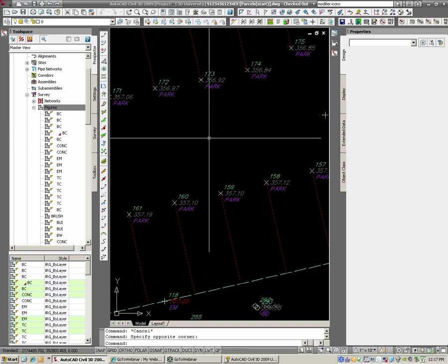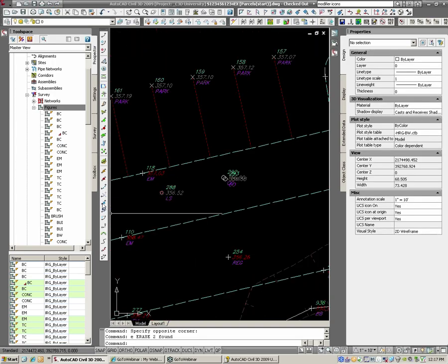So keeping that in mind, this feature line tool, unfortunately, is only the break command, not break at. So you have to be cognizant of that, or you'll have line work deleted, which you could always just not check back into Vault if you do make a mistake. You just undo checkout or undo, just right in the drawing. But to use this, we're going to use break.